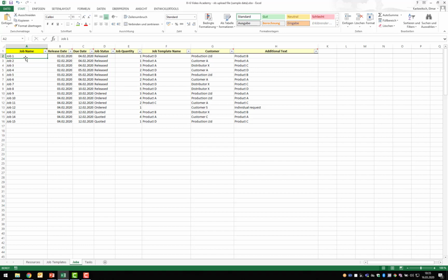And here, really, really important, the priority shall also be taken into consideration when creating this job list. That means the higher the priority, the higher you should list the jobs. So here in my case, job number 1 has the highest priority and job number 15 the lowest. So also consider this when creating that job list. A very, very common approach of defining the priority is following the due date. And you can also see here that pretty much those jobs that have a very close due date are more important than the ones that have more time from now.